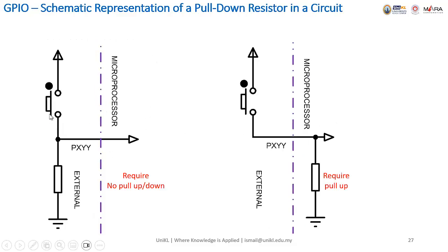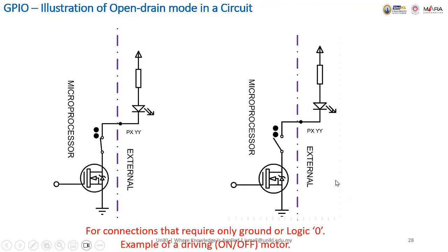The other one that we have is the resistor that we pull to ground, and you see another pin of the button connected to VCC, right? So if you see the button connected to VCC and the other one straight to the pin, the internal must be pulled down. Sorry, this one should be pulled down.